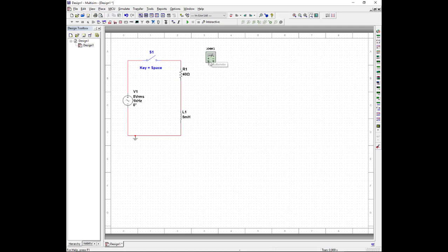And once I have it dropped, I see I have my plus and minus terminals here on my multimeter. So I'm just going to click on that, and I'll bring it over here, and you can just see the red dot appearing there. It kind of hides behind the mouse icon. Once I have the red dot there, I'll get a connection. And again, we can do it with the negative to here. So what I'm doing now is measuring the voltage drop across the resistor.